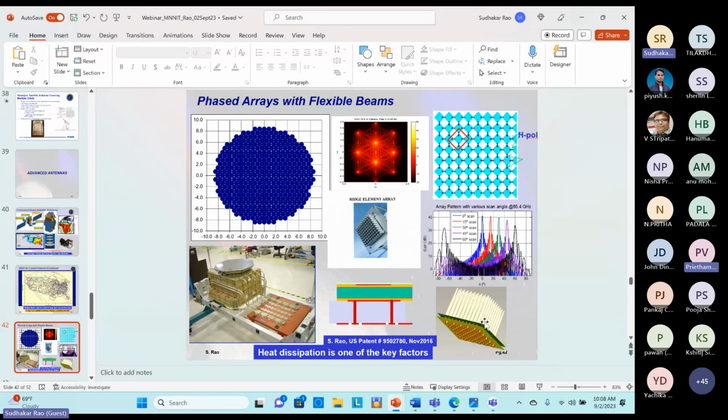Sorry, sir. I achieved the bandwidth from 3.1 to 10.1 gigahertz, sir. But it resonates at three frequencies: 3.6, 5.6, and 8.7. Yeah, but that can be used for IoT application. You can definitely use it, but it depends on how you use it for IoT type. Sometimes people tend to use the whole band, because for 5G the capacity is important. So instead of three different frequencies, narrowband resonances, people want a continuous band, so that they can design both transmit and receive with wider bandwidths. Capacity is proportional to the bandwidth, right?